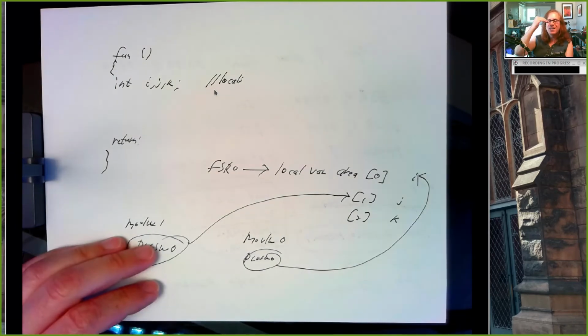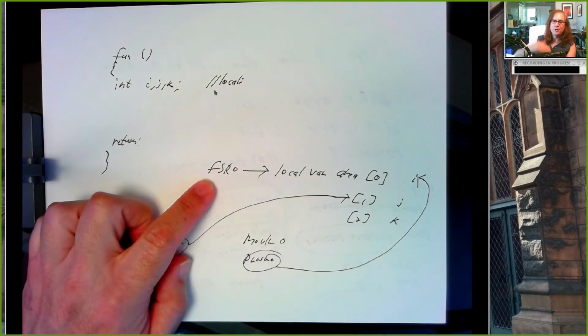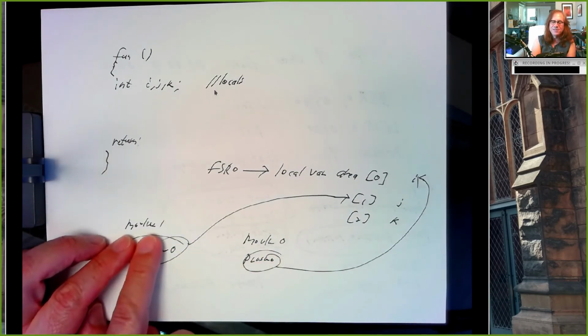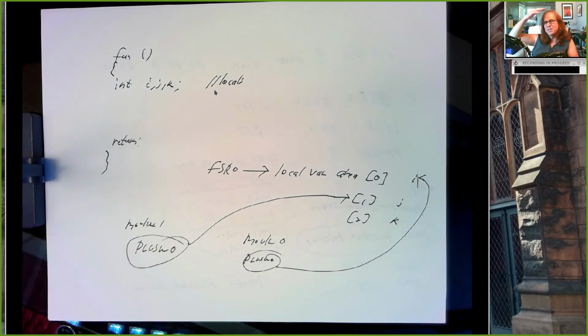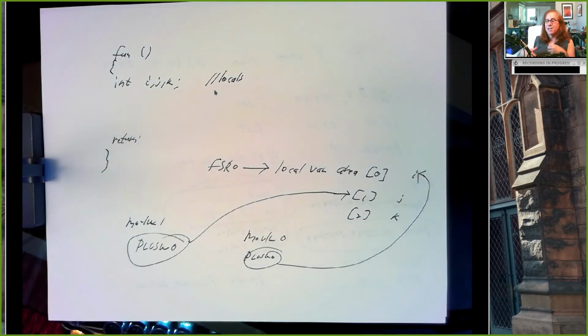Well, the way that we access those different fields is, again, we take something like FSR0, point to the beginning of this structure. And then our first integer is offset by 0. Our next integer is offset by 1. Our character array is offset by 17, and so on. So these things are useful when you start thinking about compiling from a high-level language like C into assembly language.